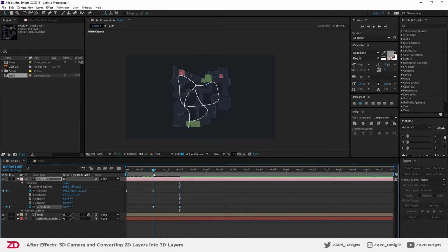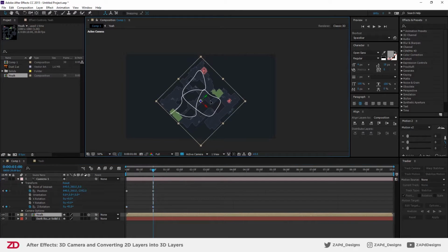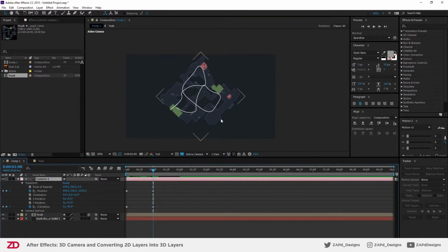And then maybe we can do a position. Maybe we can shift these over here. Oops. See what that might look like. So it's kind of zooming down here. While it's zooming down, actually let's move this. So you don't move the object. Make sure you don't do that, because we're just doing camera animation. You want the object here to be completely still. Don't do any keyframes on the object. Do all camera work unless you want to move the object for some reason. But in this example, don't.